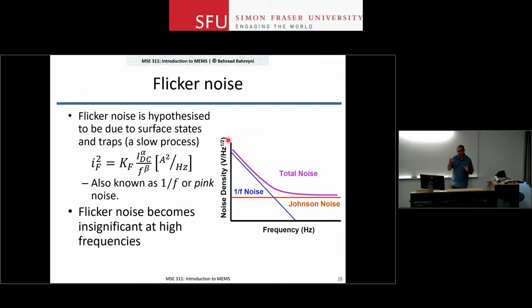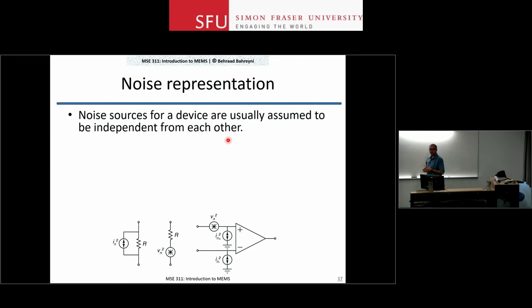So let's assume that in an electronic system we figured out the noise sources. How do we represent them? Well, resistors are the only ones that produce noise. Remember, noise was associated with dissipation of energy. Capacitors and inductors do not dissipate energy, so they do not have noise. So for resistors, this is how we show noise. Amplifiers, let's say an op amp in this case, have a combination of transistors and resistors inside them, right? So you see the collective noise response of all of those components at the output of the op amp.